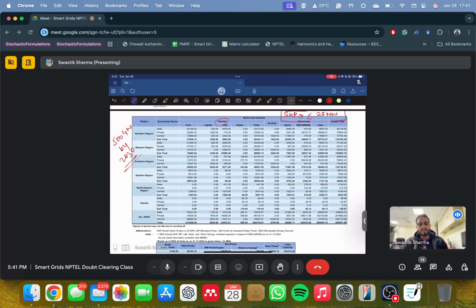Hydropower plants can ramp up very quickly. Thermal power plants can't ramp up. What do I mean by ramp up? It's increasing its generation in a given amount of time, right? Hydropower plants can do it very quickly, but thermal power plants can't. So it's not that hydroelectric power plants can't generate much electricity. They can, but that's not the correct reason.